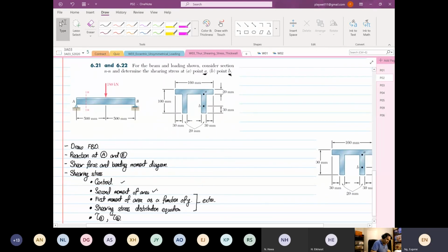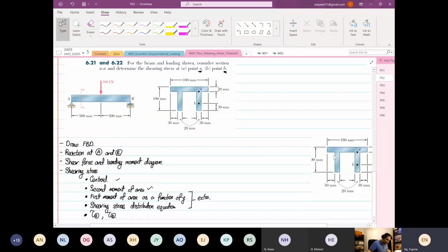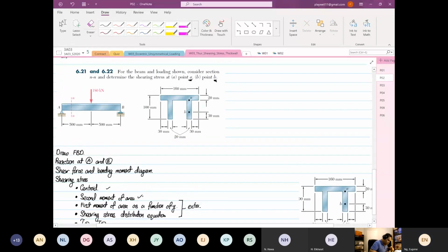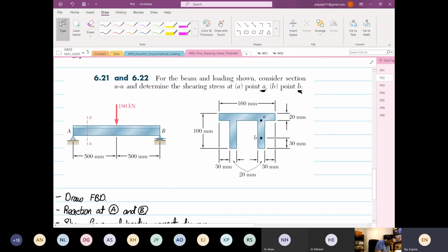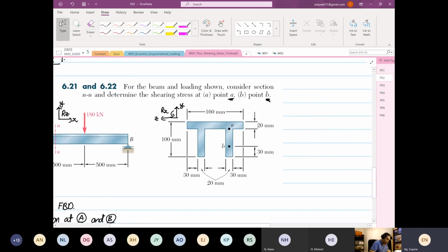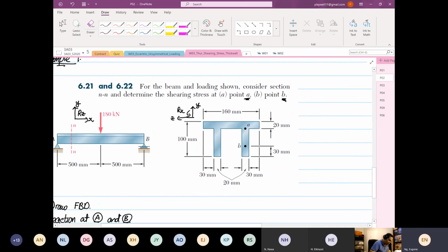So we're going to firstly construct our free body diagram. Very quickly, you guys are really expert. Before we go into our free body diagram, based on this figure, we're going to call this our X and our Y, and then this over here is our rotation about Z. On the next diagram is a cross section view, and this is our Y, and this is our Z, and this is our rotation about X. Okay, we get that clear first.